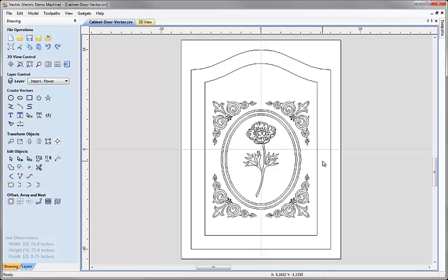Then we again use the snap grid to help us accurately sketch an ellipse. We offset that ellipse inwards to create the rings in the middle of the part. Then we imported a piece of vector clipart, grouped that together, rotated it, positioned it in the corner and made mirrored copies of it. And then finally imported our flower design and then just scaled that to fit and then moved all our data down 1 inch, again making use of the snap grid function. In the companion tutorial to this, we're going to take this data and create toolpaths on it. That concludes this example.